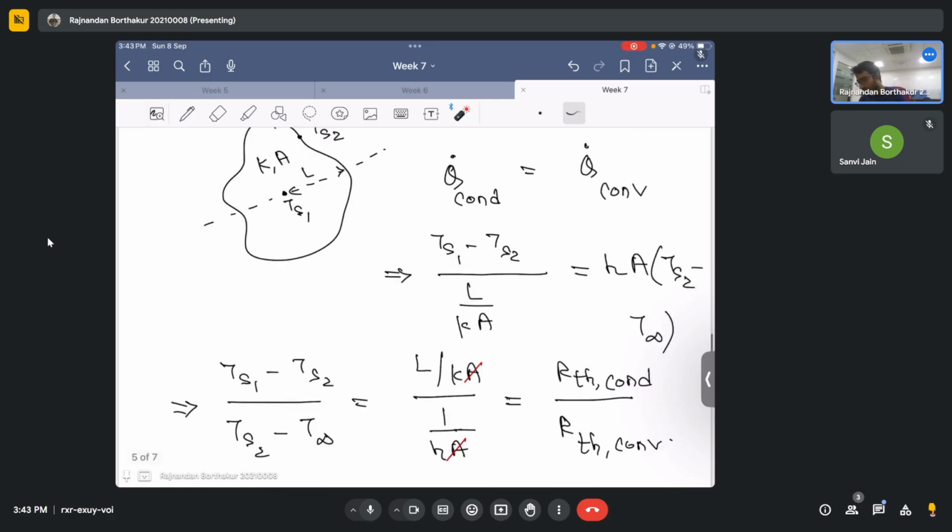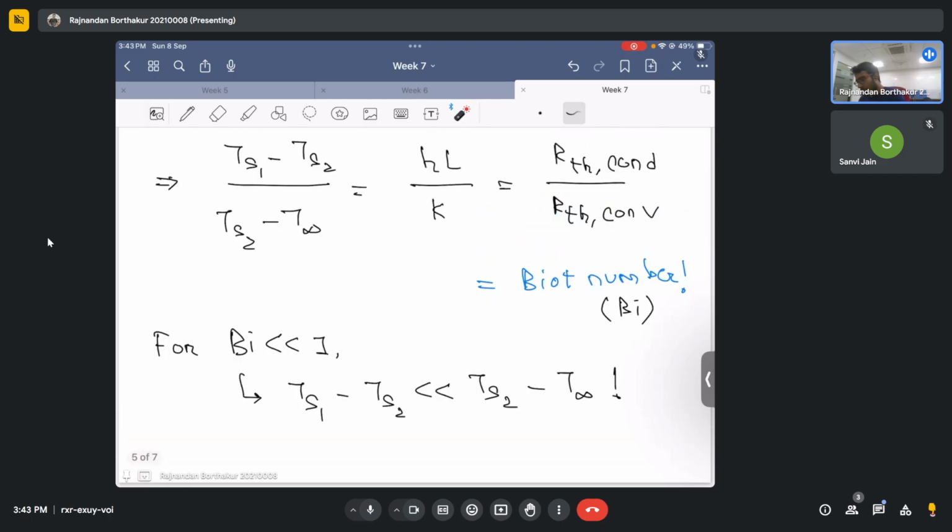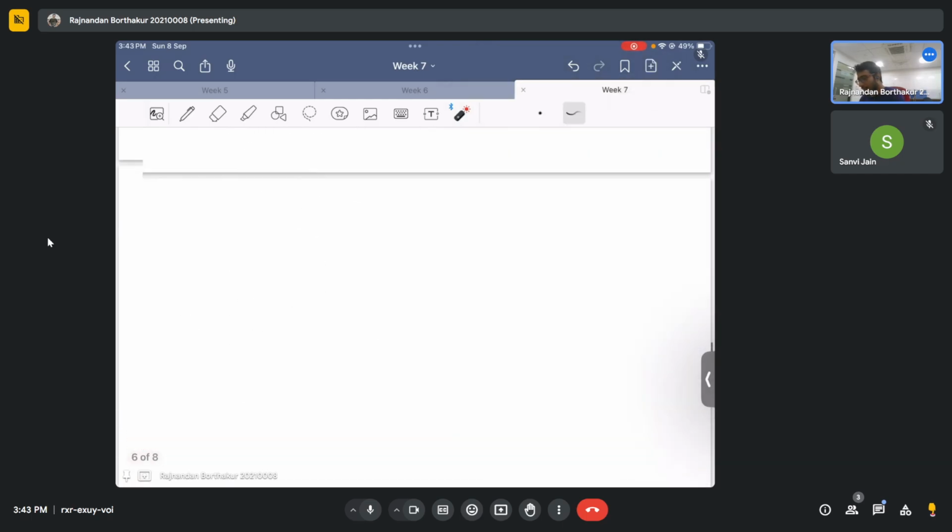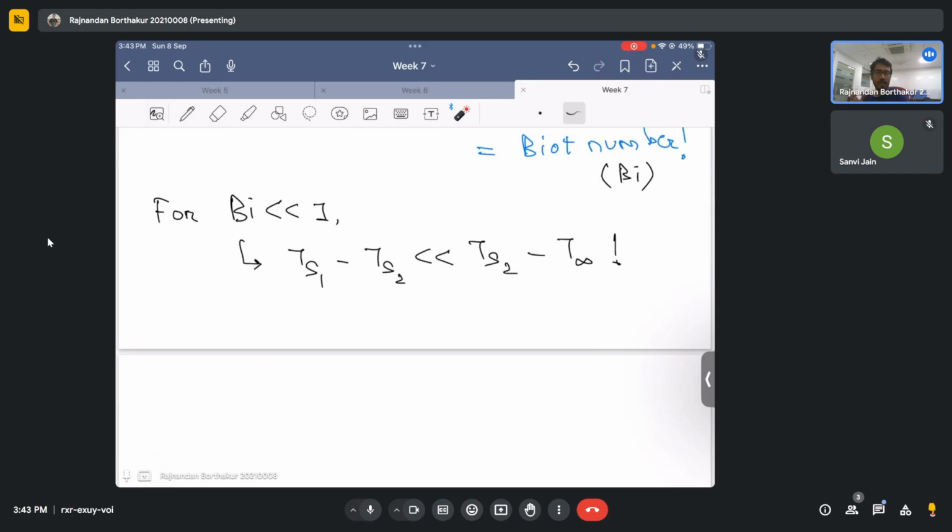So this means now you have understood when the lumped capacitance model is valid, and when I say that the conduction resistance within the body is negligible, or the other way around, the temperature distribution is just a function of time, or your temperature is not varying spatially. All this signifies and directs to the fact that the Biot number is very much less than 1. Now, if I say it's very much less than 1, how much less than 1? That's the second question that we have, right?